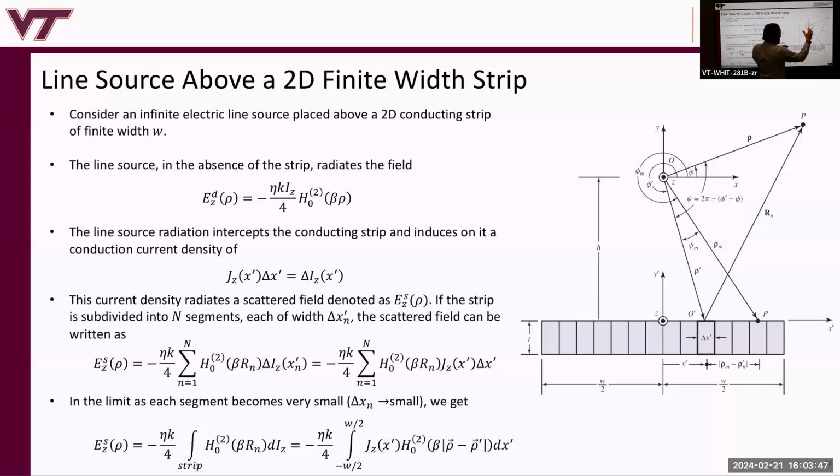That cylindrical wave is going to expand and impinge upon this scattering obstacle, and it's going to induce currents on the obstacle because of the conductivity of the obstacle. Those currents then will radiate, right? Once we have induced currents, then it's easy to calculate what the radiated field is due to those induced currents by using the vector potential approach, right?